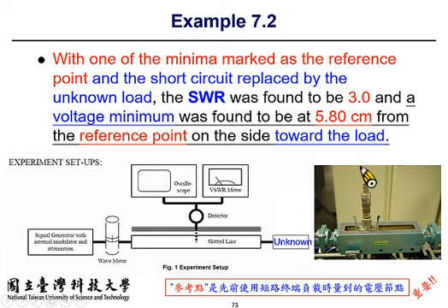So by moving the probe to the right or to the left, you can observe the variation of the electromagnetic wave within the transmission line, and you can see that at certain points the swing of the sinusoidal signal becomes larger, and at other positions the dynamic range of the sinusoidal signal becomes smaller. So if you record the maximum voltage level at different positions, you will end up with the so-called standing wave pattern, as we see from the first slide. It goes up and down and up and down at the different positions.